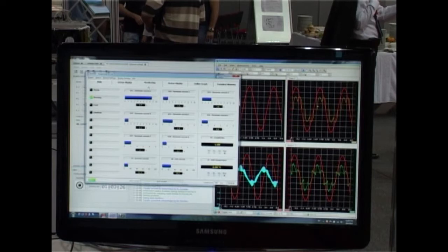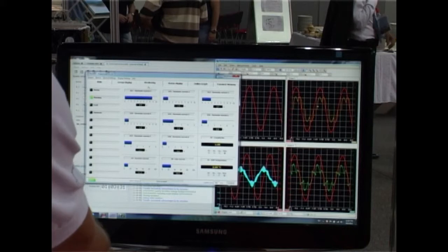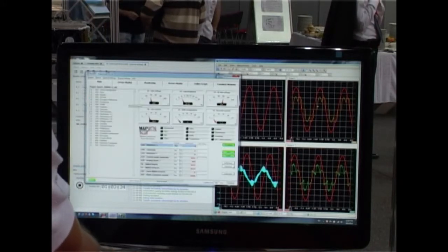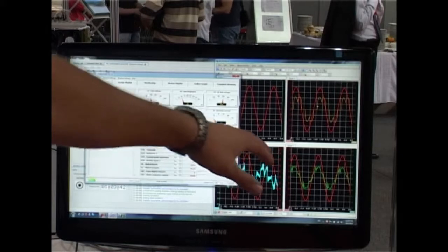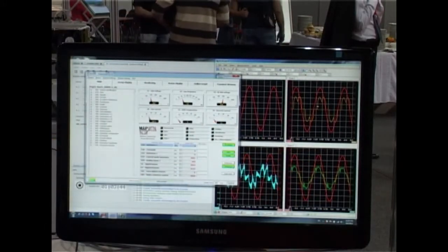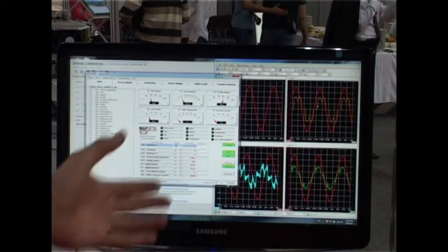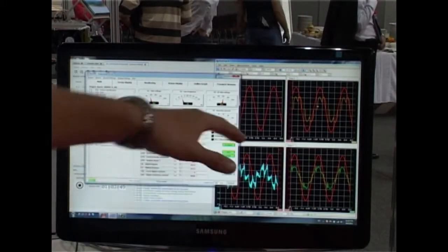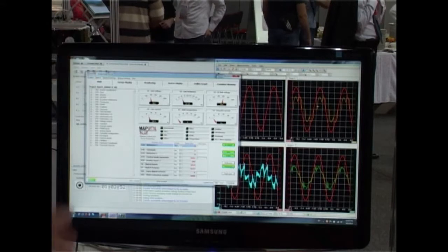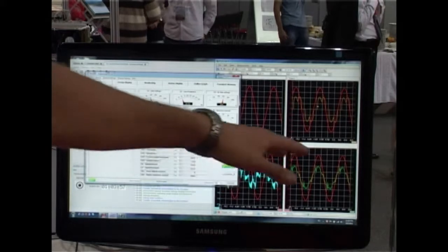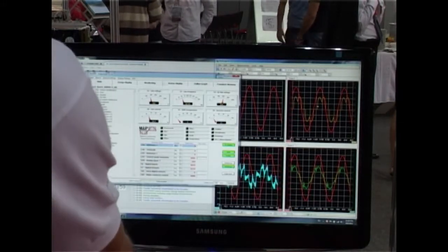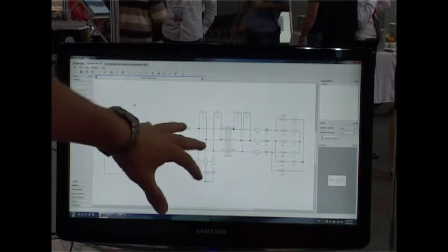Like this. Now I'm about to start the harmonic suppression function of this filter. We can immediately see the effect on the grid current. It now looks more like a sine wave, which is what we really wanted to achieve. Of course, there is some high frequency noise because the filter suppresses only up to the 15th harmonic, and the switching frequency is not that well suppressed by the passive filter in front of the inverter.